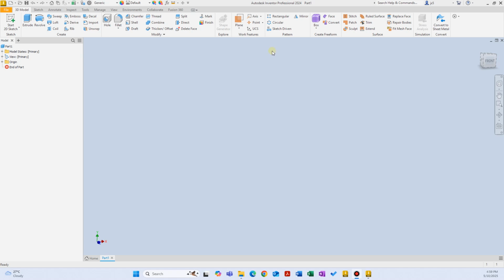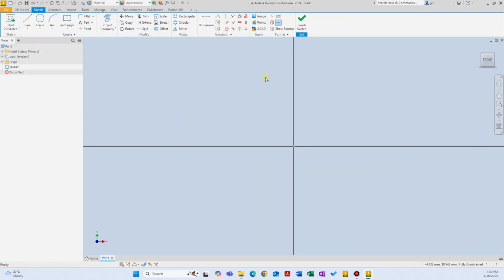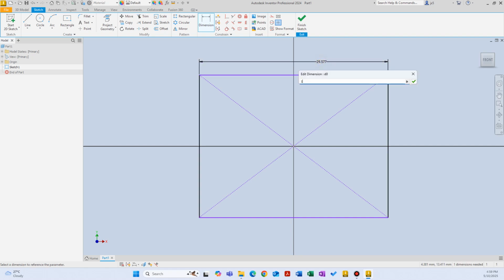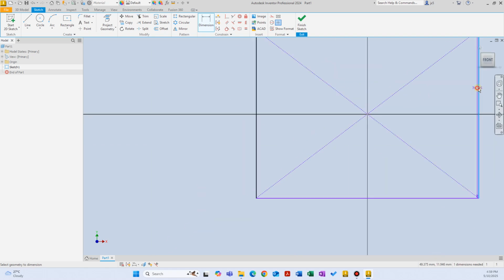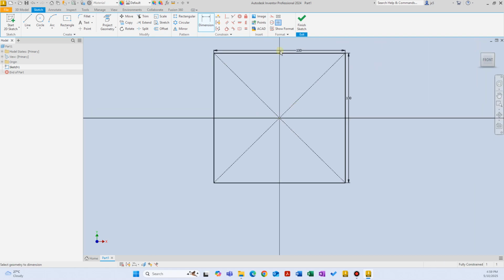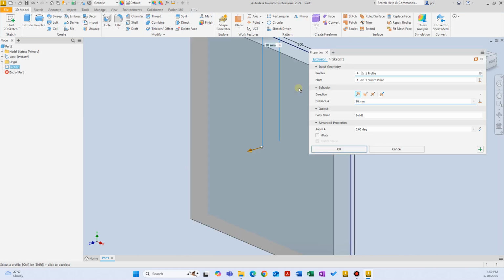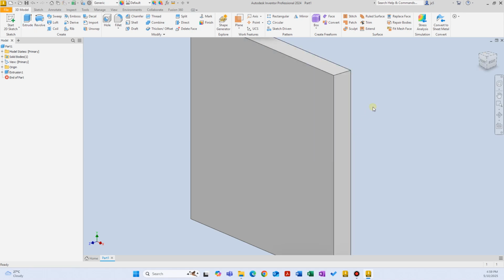So we're going to give some examples for the rectangular pattern, circular pattern, mirror pattern, and sketch-driven pattern, which is the only difference, I think, if we compare this menu with the sketch patterns. So let's just draw a simple geometry. Let's use the 2-point center rectangle, and let's say it is a square, 100 millimeters by 100 millimeters. And now let's finish that sketch and right click extrude, and let's extrude it by 10 millimeters.